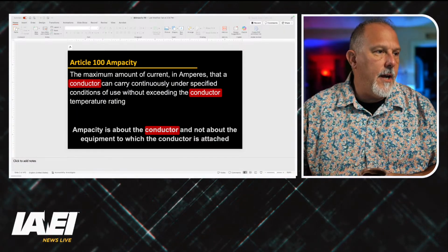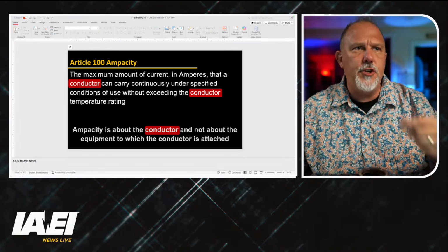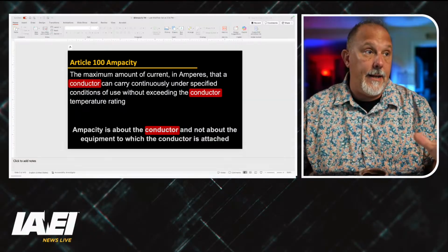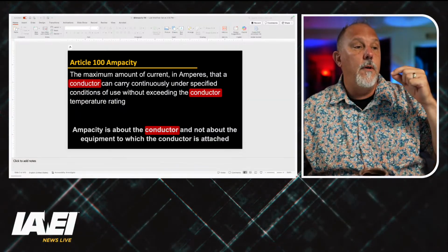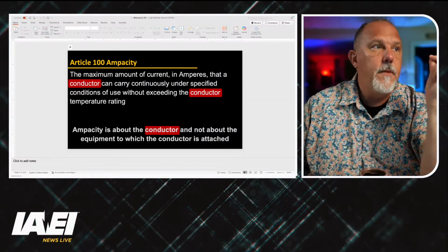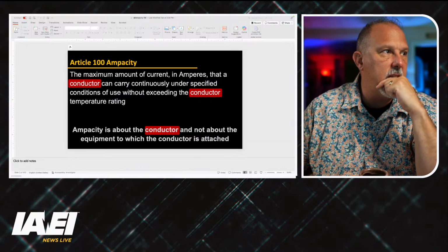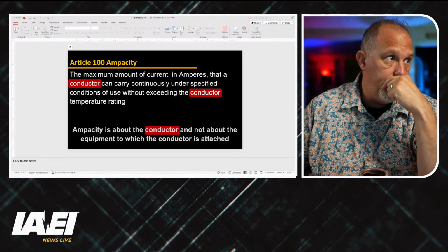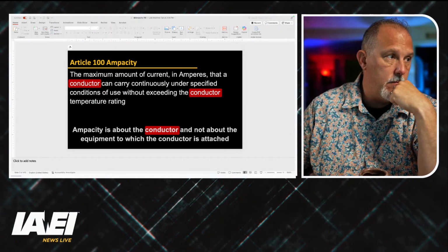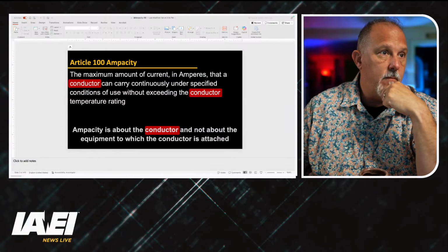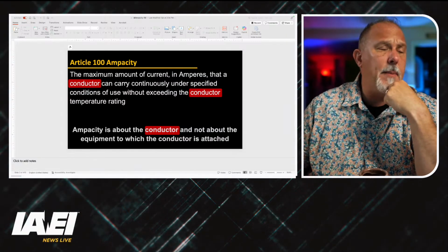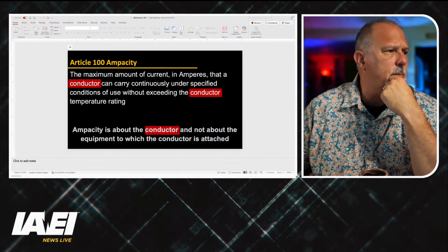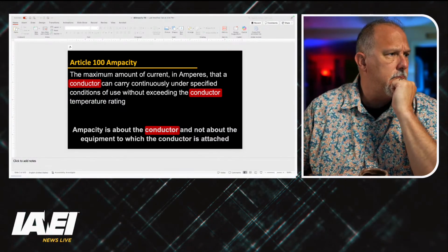All right, so then I'm not going to go through the engineering supervision. You can calculate, etc. So that's basically 310.14. It speaks to the ampacity value. So how do we get there? Let's go back to 240.4. Oh, that was in the parent text of 240.4. As specified in 310.14. So what gets me to 310.15?